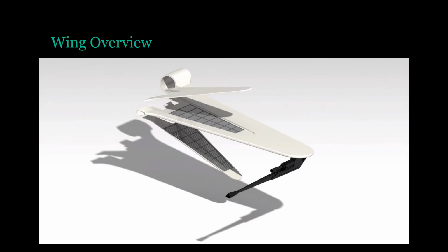The wing subassembly consists of three main parts: the central wing, the two winglets, and the cannon. The central wing was modeled by tracing its profile using the sketch tracer toolbench, and then completing the rest of the features using generative shape design. The hardest part of modeling the central wing was the mounting point between the wing root and the engine casings, which involved multiple different curved surfaces in order to maintain the curvature of the ARC 170's wing and also allow it to mount against the curved casings on the engine.